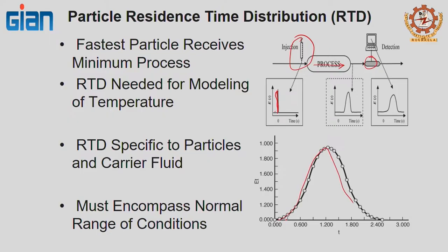Initially certain particles come through, and then certain particles may take even longer. From a processing point of view, those particles have more difficulty receiving adequate treatment, whereas I am concerned about this particle here, because this particle is spending less time in my holding tube. So, I want to make sure that my processing is done properly, so that this particle is properly treated.